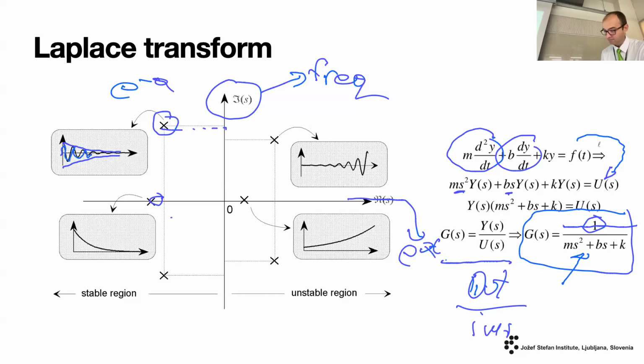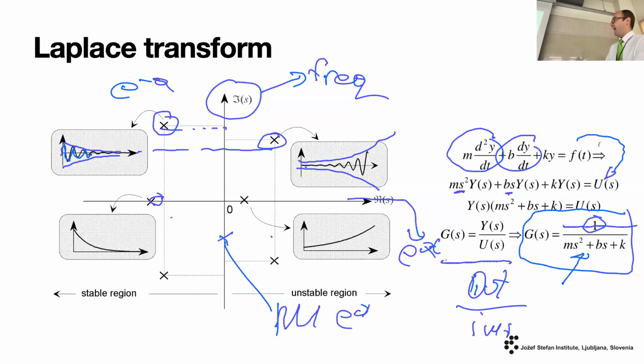If we go on the other side, we have a different frequency, a little lower than this one, but we have a positive exponential. So this will grow over time. If we have a pole here, this means that we will just have oscillation because we're multiplied by e to the power of 0. And these poles are actually defining the resonant frequencies in our system. If you have ever done distribution of relaxation times, these frequencies correspond to the peaks in the DRT.